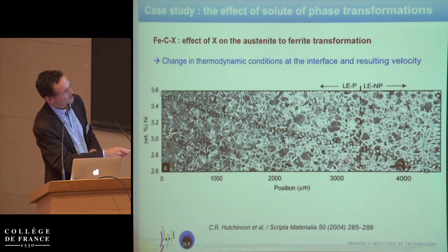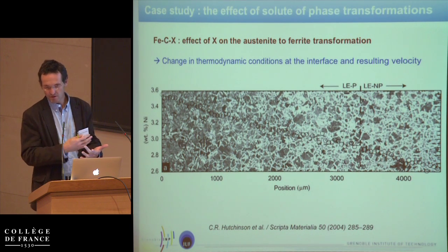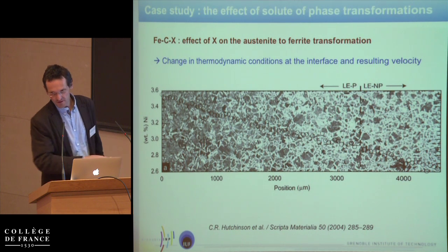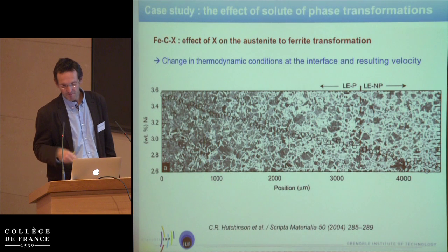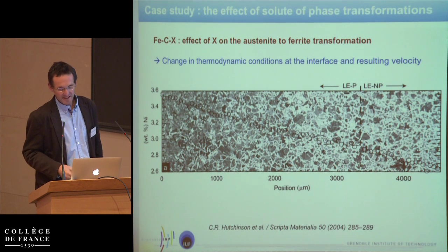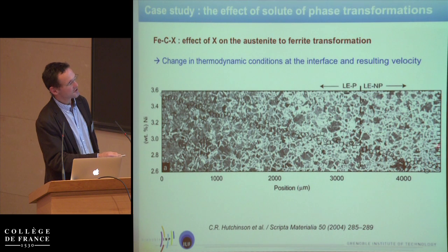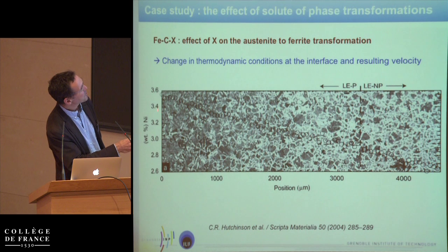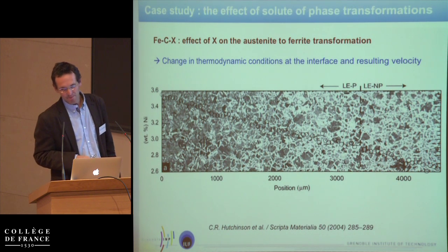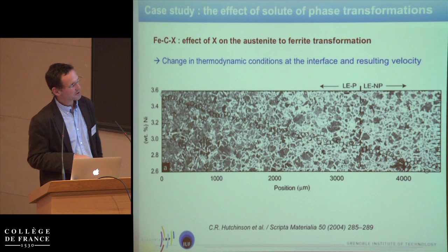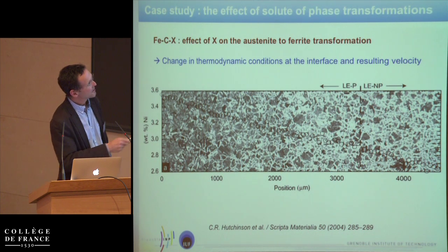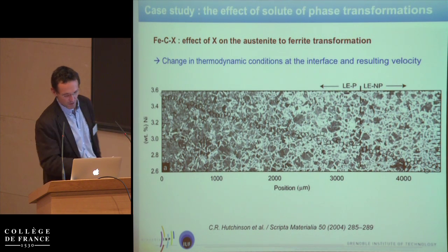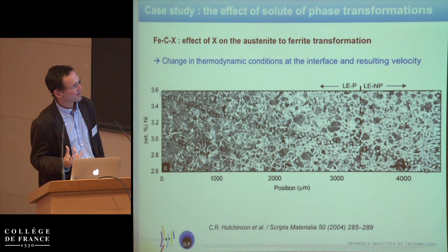And you can decide, depending on the microstructure that you could watch at a higher resolution with another tool, what was the boundary between the two thermodynamic conditions. So here it's typically microstructural control, alloy design, to know, okay, if you want a fast or slow kinetics of your transformation, you can put the chemistry either at 3.4 or 3.2% here. This would have been quite difficult to show with individual alloys, because the difference in content here is quite small. So to do that with individual alloys is quite difficult.